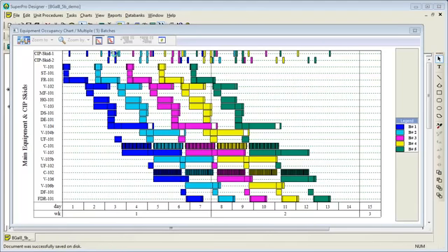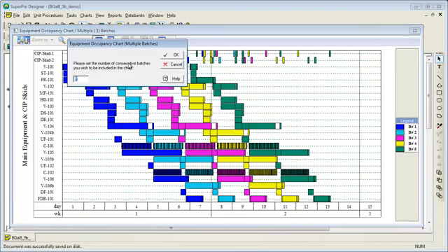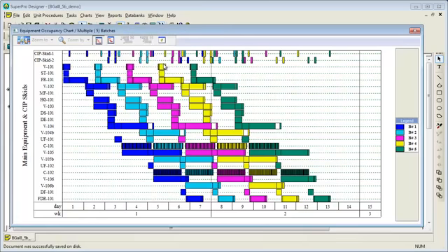Note that it is possible to customize this chart and other charts in SuperPro by right-clicking and choosing the number of batches or modifying the style of the chart in order to include or exclude certain information. It is also possible to change the style of the calendar information that shows up at the bottom of the chart.